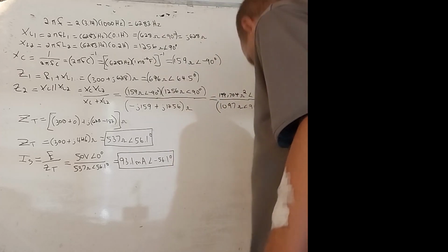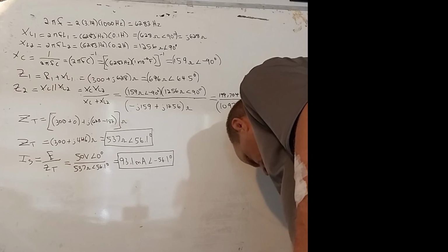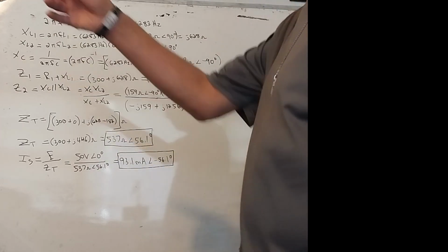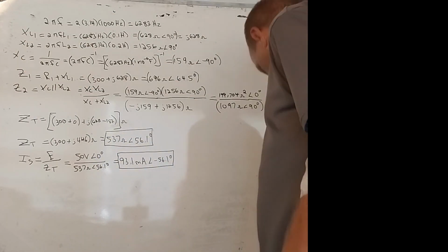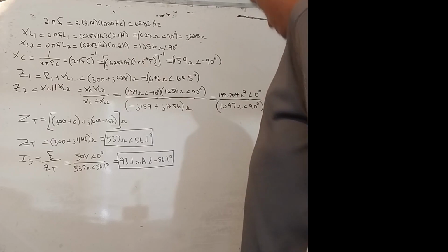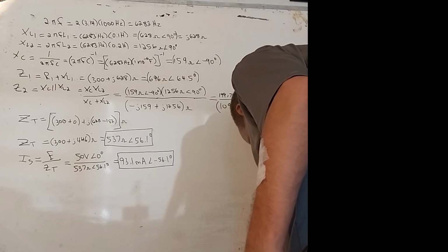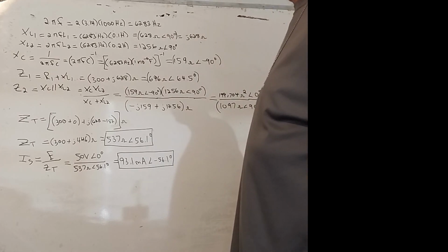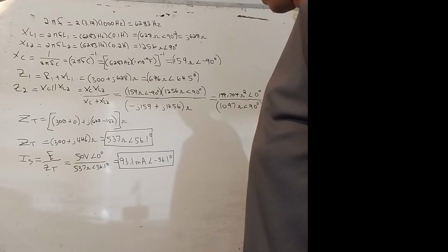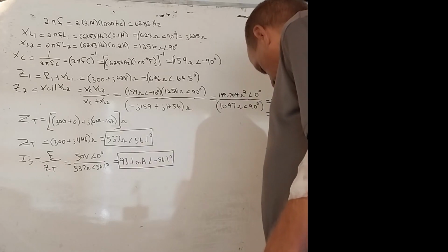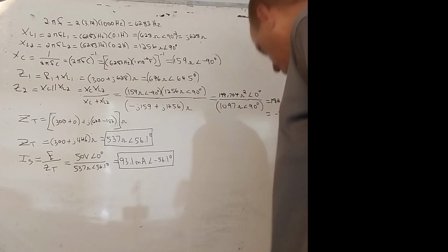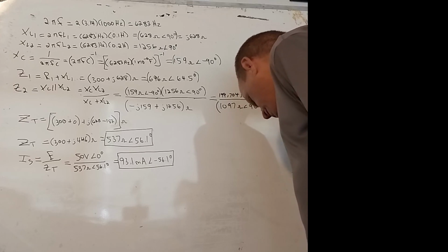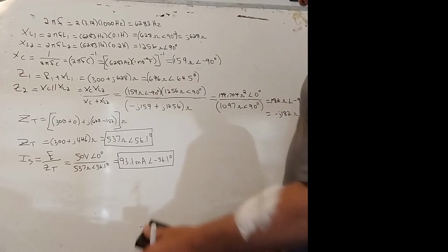V1 in this problem is the voltage across the XL2 or L2, and that's I2 as well. Which is funny because you would think that V1 would have I1, but no. I2 is the current flowing through the element where V1 is measured across. The capacitive load is I1 that we're going to find. We're also going to find the average power delivered to the network and the power factor of the network, and indicate whether it is leading or lagging.